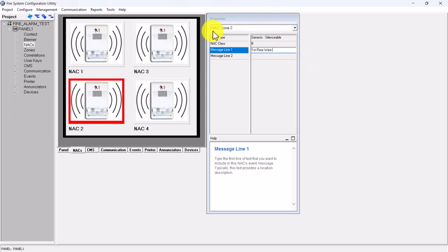How I like to do it is once the system is installed and it's powered up, we turn on the system, we plug in all the wires, make sure all the wires are clear, plug the wires into the data loop, let the data loop find all of the devices, let it map all of the devices, give it the addresses. Once it's finished, then you upload the loop.